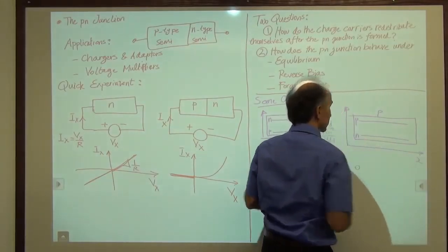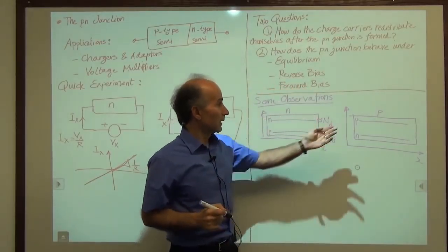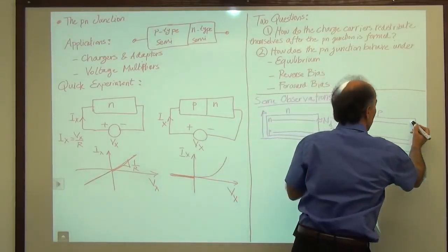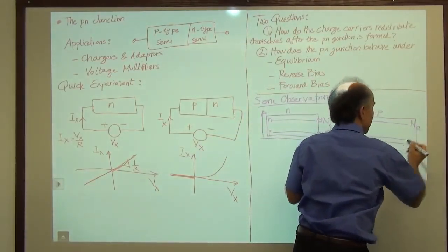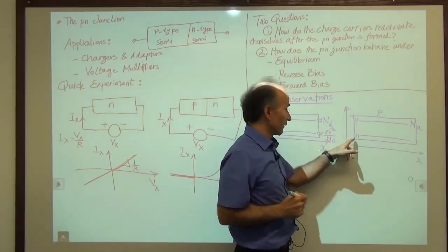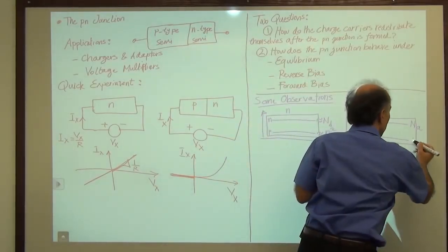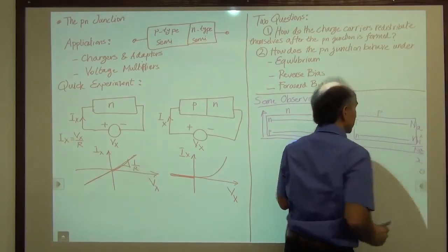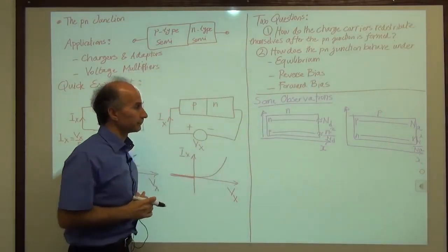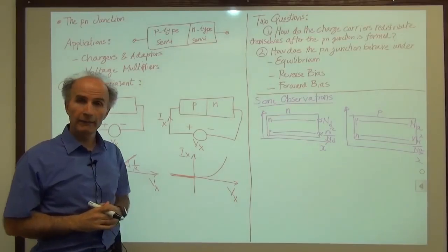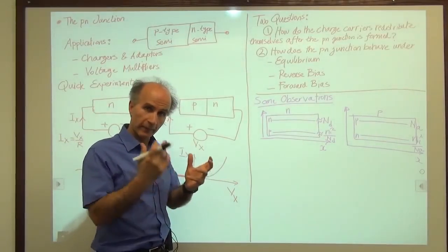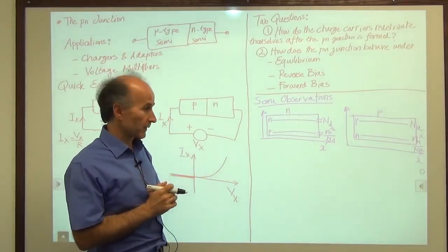So that's N. And we saw that the number of holes per cubic centimeter is given by the concentration of acceptor atoms, whereas the number of electrons is given by Ni squared over Na. I hope you can read this on the screen. Okay, so that's just a quick summary of what we have learned before for N-type and P-type doped semiconductors.